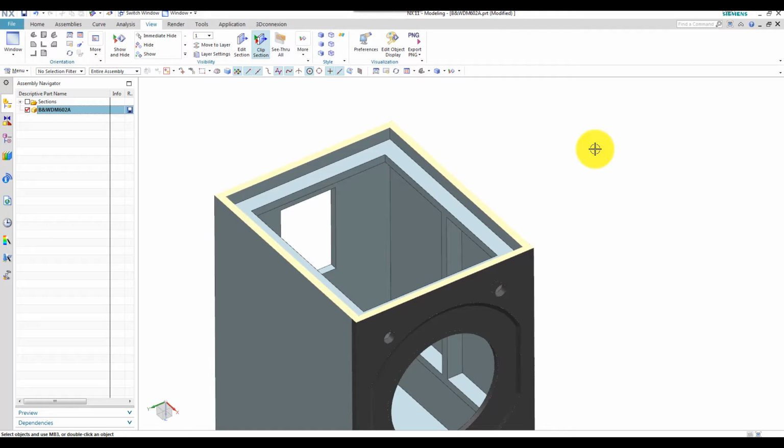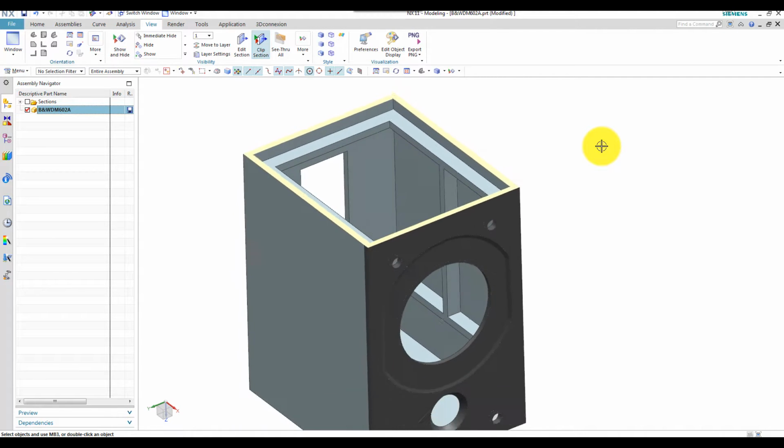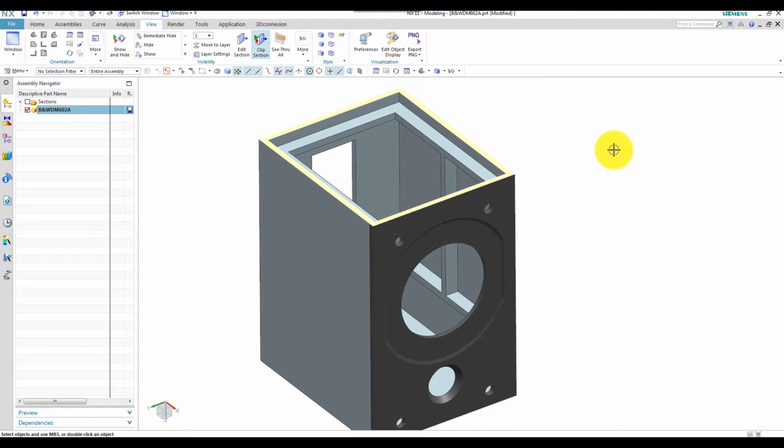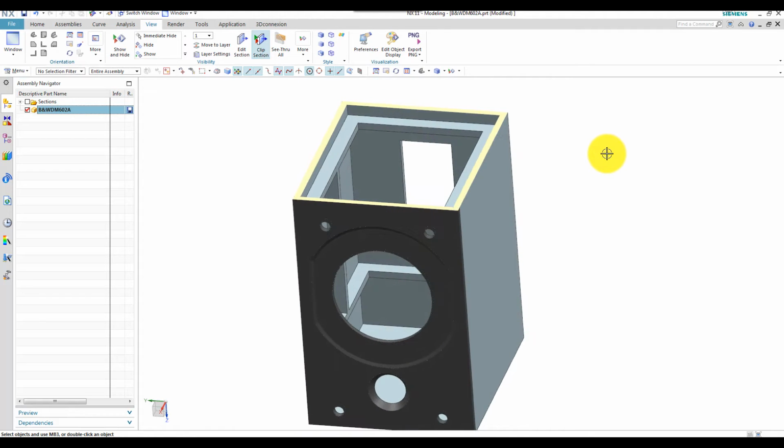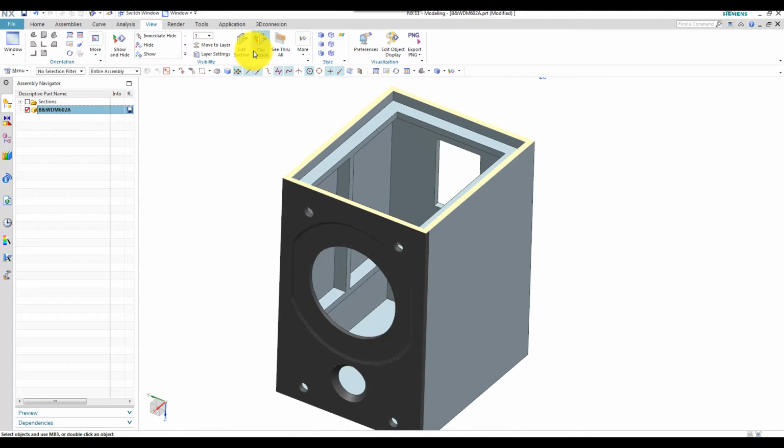So that means I have the same solid, and when I then open the FEM file, it will remesh itself when you update it, and then you don't have to use more glue commands because from a topology view, we have the same geometry.